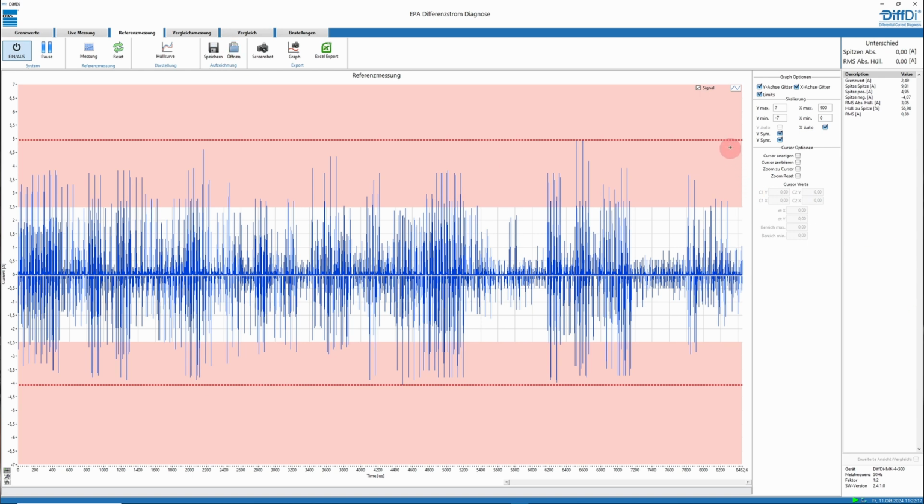The red dashed line shows the highest current pulse. In our example, there are relatively many current peaks in the red range, and the dashed line is therefore also well into the red range. The sum and the height of the current peaks that occur and reach the red area should be evaluated here. The more and higher the peaks are, the greater the load on the motor. We now know that our motor is exposed to quite a high load due to bearing currents.